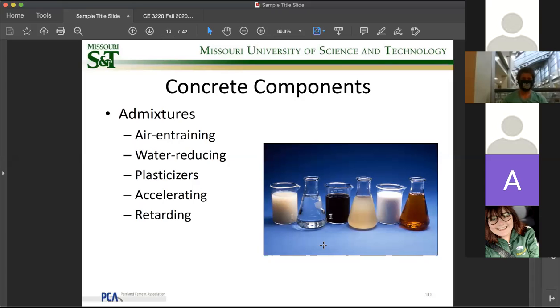And we have water reducing agents. Sometimes what happens is we add a lot of water at the beginning to do a fast construction, and after the concrete is poured, we want the concrete to achieve early age strength, so we use a water reducing agent to extract the water out, okay? And we also have plasticizers, okay? In terms of more polymer content, essentially, by adding polymer to the concrete, it becomes more pasty-ish, so it also flows.